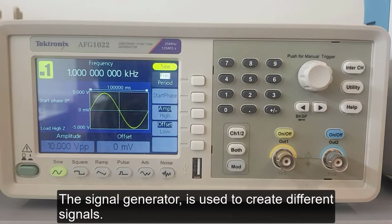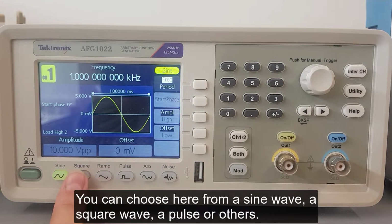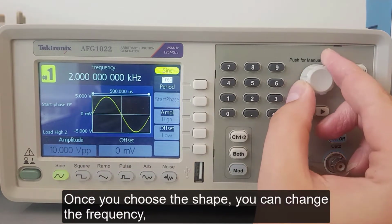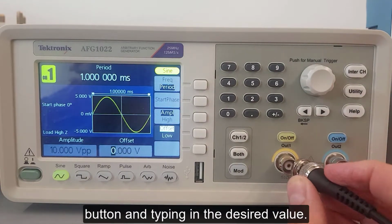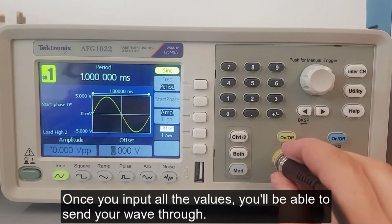The signal generator is used to create different signals. You can choose here from a sine wave, a square wave, a pulse, or others. Once you choose the shape, you can change the frequency, the period, the start phase, and add an offset by pressing the corresponding button and typing in the desired value. Once you input all the values, you'll be able to send your wave through.